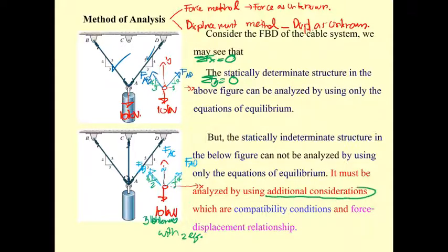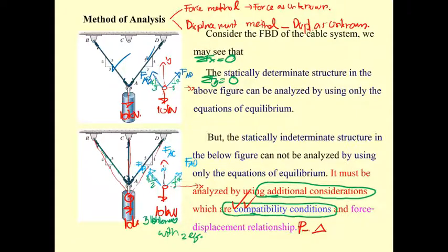You're going to have additional consideration of this structure by considering the compatibility condition. That means you're going to consider how this structure is going to change under the application of the force. For sure, this one is going to have some kind of deflection. So the deflection of this structure is going to come into play in this analysis. We call it the compatibility condition. And since the deflection is based on the force, we also need the force displacement